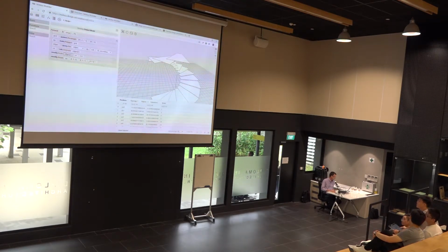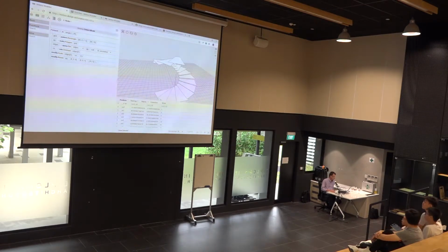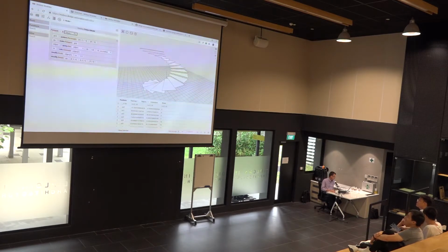Double click on this, then you see the code in this model. We can see here a very typical bit of code. We say we're going to make 20 steps in this staircase, and we say from range 1 to 20. So actually it's 19 steps, starting with 1. And then we say we're going to make a rectangle, which is actually just 4 points. This is the 4 points here, and then we make a polygon.